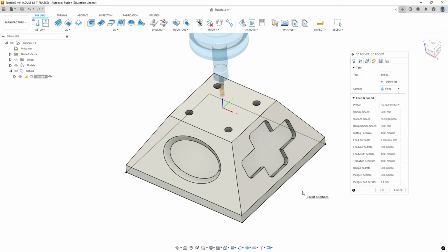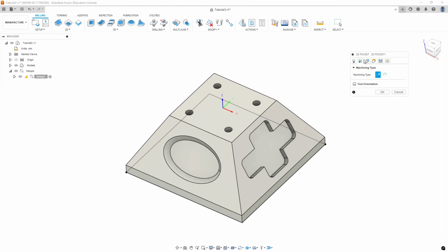And it does appear we're working in metric units. That won't really matter for what we're doing here. What we're focusing on is the second tab here called multi-axis. So we're going to accept our tool as default, pick the multi-axis tab, and for the pocket command, you actually have a wrap function where you could wrap this around a cylinder.